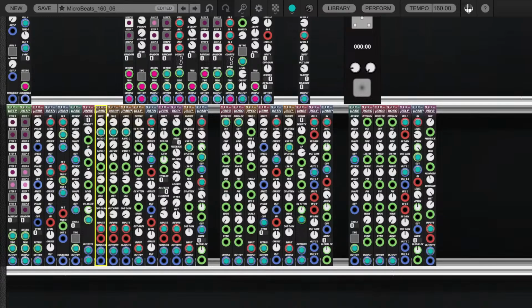we have 3 modal bandpass filters. Kind of like additive synthesis. We add partials because a resonating filter outputs a sine wave basically. And we can stack those in different ratios. That's why we have ratio coarse and ratio fine to do the same thing like additive synthesis does. We stack these sine waves, stack these partials to generate a more interesting tone.